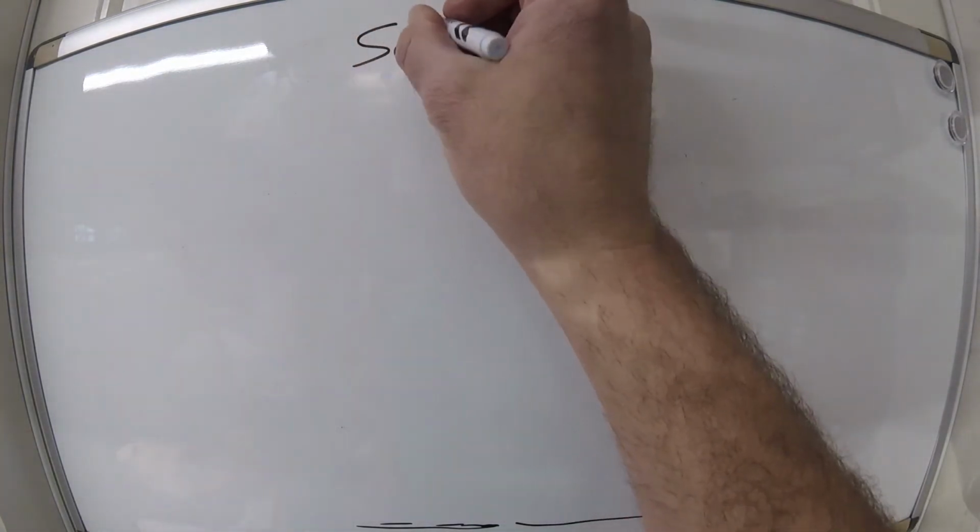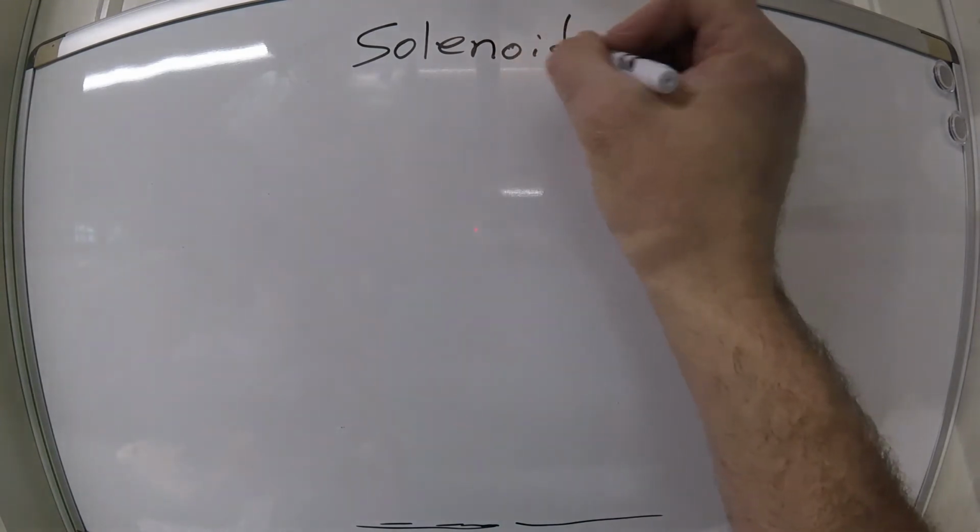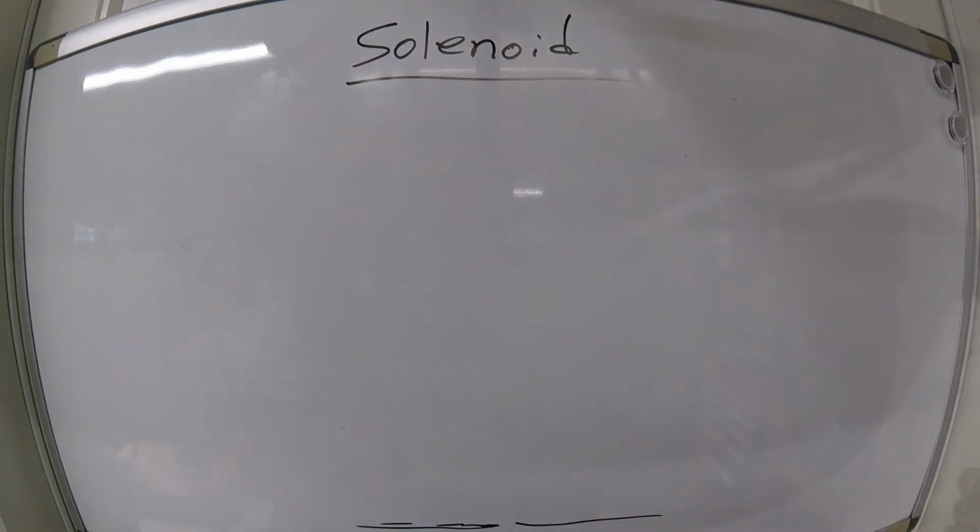We're almost finished with terminology. One of the next things we want to talk about in automotive electricity is a solenoid. You may have heard of this. A solenoid is a very simple device. It's a coil of wire, usually with a hollow hole in the center with an iron slug that can move inside, and that iron slug is usually spring-loaded so that it returns to position. But this coil, when you put electricity to it, forms an electromagnet. And so we can use that to do work.